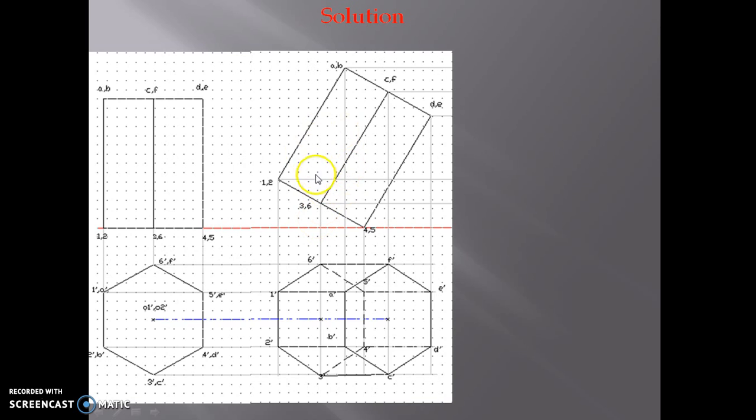So this is what is called rotate and redraw the first front view in the second stage. Now from this second front view and first top view, construct this second top view. According to the visibility, looking from top, see which base edges and which vertical edges of this second front view are seen. Complete, draw the projectors vertically in this second top view.